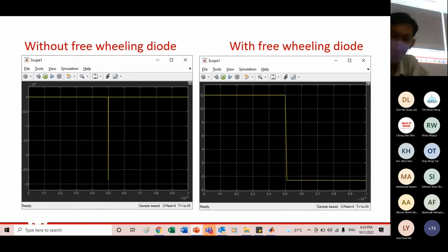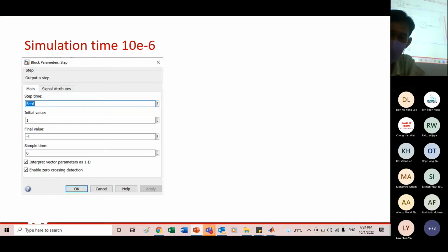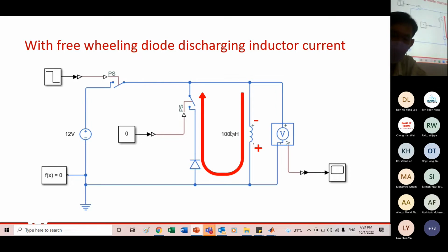Okay. So this is the phenomenon where you will see, this inductor, right? It's actually in real application, they are motor. Okay, they are motor. All right. So every time if you try to control motor, you need to have a diode parallel with, or else it will damage your, the chip itself. Now, especially for mechatronics student, you're dealing a lot with motor, right? Small little motor control thing. One of the example